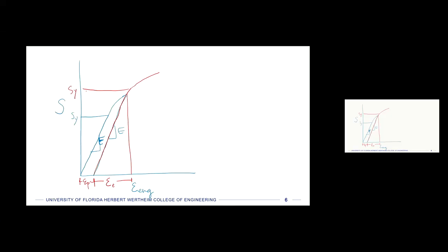And this happens based on what we talked about in the very first lecture, where if we keep pulling on a material past the elastic point, then the crystalline lattices move, dislocations are introduced, and as dislocations build up, they resist additional slips. So that's where this comes from.